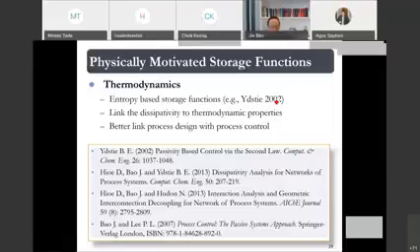Now, for any of you who has ever worked on Lyapunov design for nonlinear systems, you probably remember that it's always very difficult to determine the Lyapunov function, because Lyapunov stability is a sufficient condition, not necessary. So if we can find a Lyapunov function such that dV/dt is less than 0, then you can show the stability of the equilibrium point. But if we can't find such a Lyapunov function, then the study is non-conclusive.